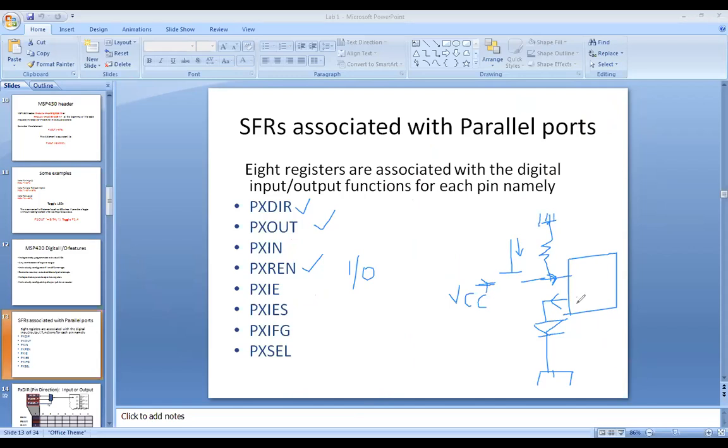So all of us know LED is available at P1.0 and P1.6. We can work with red LED at 1.0, green LED at 1.6. So we will now investigate at what point this launchpad switch is connected. Let me break the ice. It is available at 1.3. One push button at 1.1 and another at 1.3.